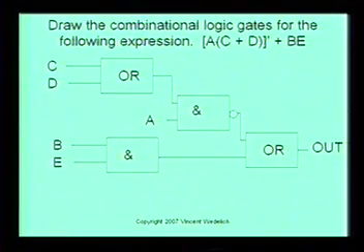And you can see I used blocks in here instead of the actual symbols that we saw earlier. The reason I did that is because a lot of times you have ISA binary logic diagrams. They'll ask you for that in a contract. They'll say, I want an ISA binary logic diagram. And what they mean is these are ISA type symbols instead of the conventional gates that you see in electronics.